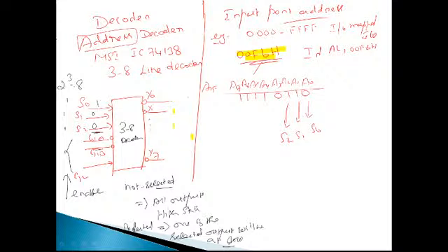So what will happen? Whenever this line of program is executed, the processor would have placed address 00F6. When the 00F6 pattern comes, A2, A1, A0 will be 110. Accordingly, S2, S1, S0 is also 110, and 110 is 6. So Y6 will become low, while every other output stays high. When selected, Y6 is pulled to low level during that particular moment. This is exactly what we wanted.